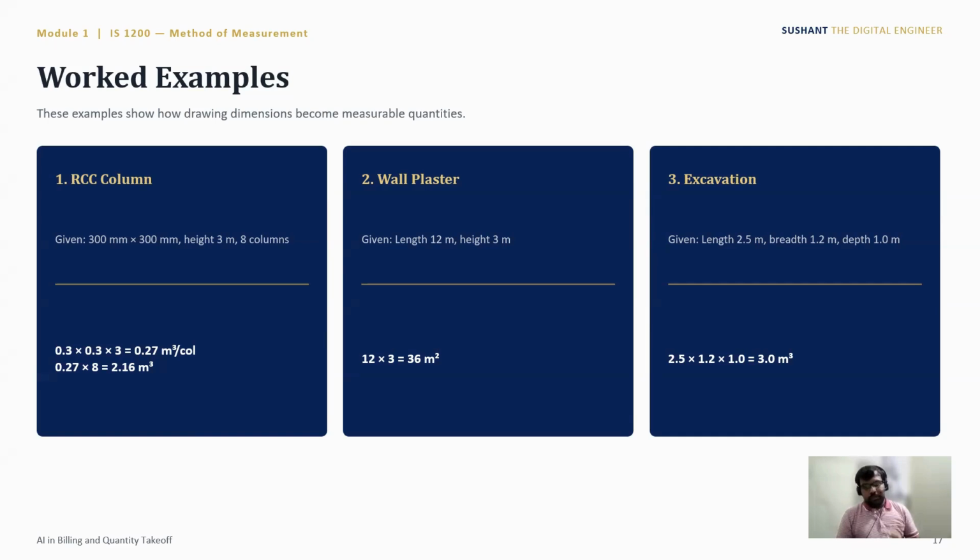It looks simple, but when the project is huge, like 1 lakh square feet, 50,000 square feet, a multi-story building or high-rise building, the quantities involve multiple activities and multiple items of work. You should calculate the quantity item-wise. In excavation, there is lift-wise calculation. In RCC and PCC, there is a mix design. So we need to calculate with respect to everything.